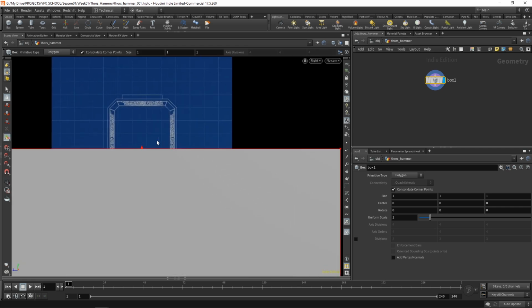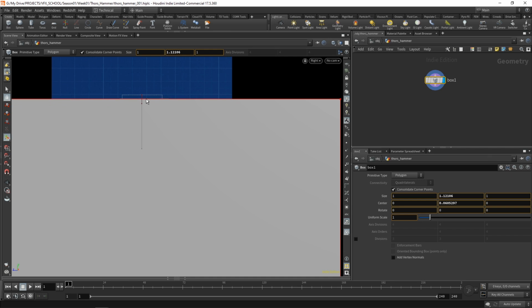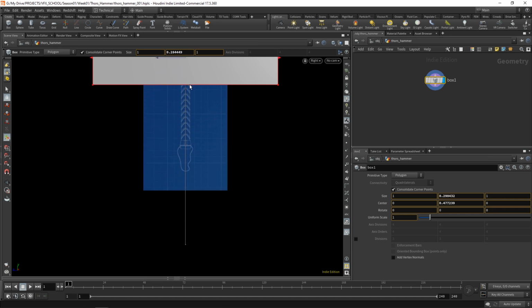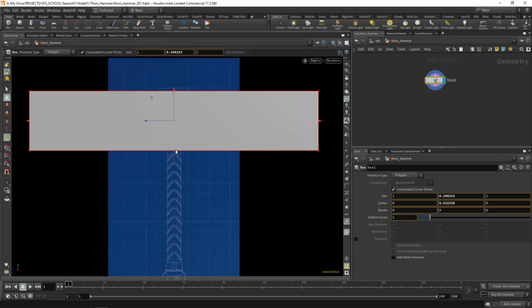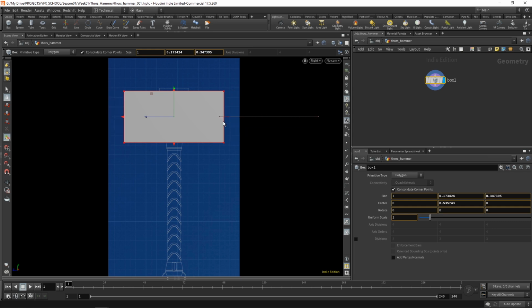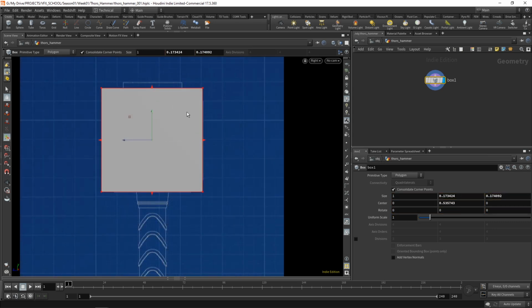Now I'm gonna adjust the height of the box there. I'm gonna grab the bottom, pull it up. There. Next, regarding the sides, if you know it's going to be symmetrical, we can use Shift while we drag one of the arrows, and that's going to apply the same offset to the other side. Yeah, this size is good. We're going to adjust the dimensions here, just make sure it's a better match. So let's say 174 and 174. Okay, that way we have a perfect square.